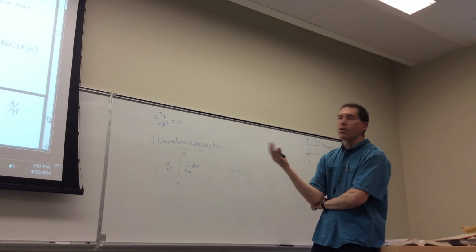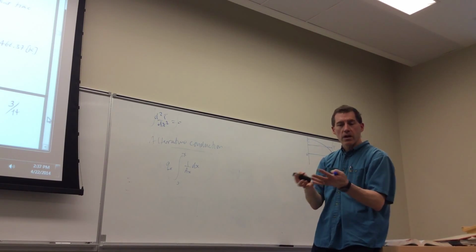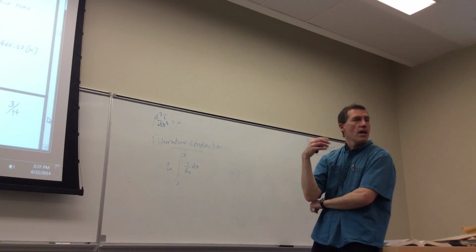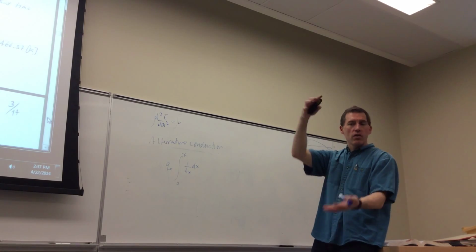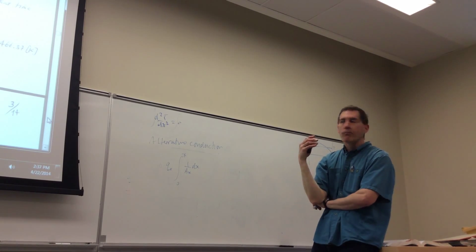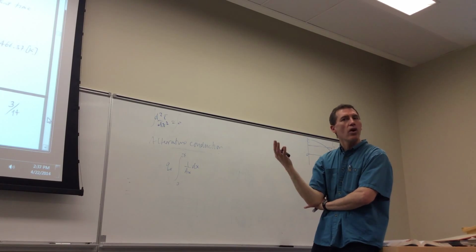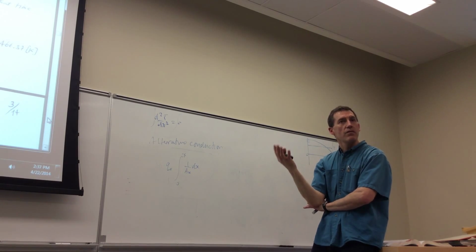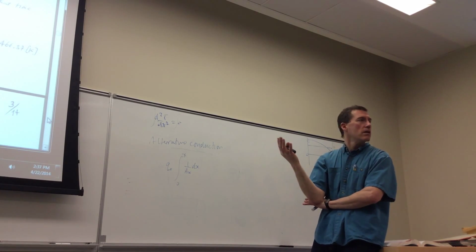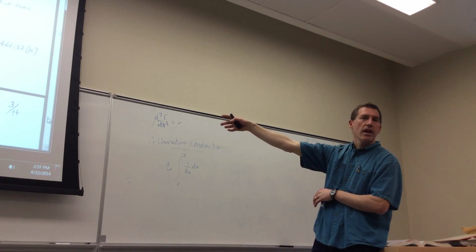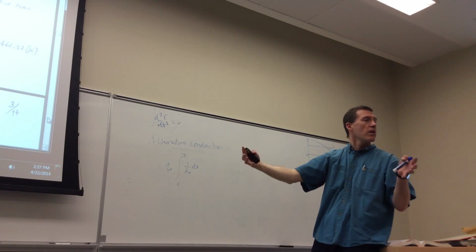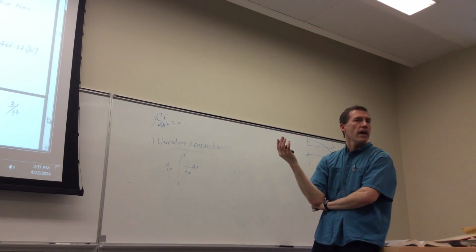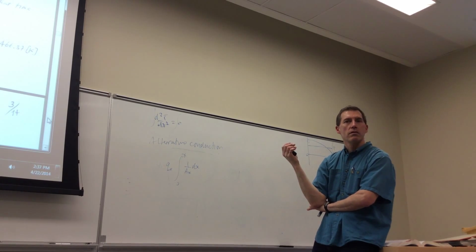So just be prepared. The only hard part about the heat exchanger problem is figuring out what geometry or what condition you have, what equation to use for epsilon or NTU, and whether you're calculating all or part of the overall U. Make sure when you do the overall U calculation, or the UA, to get the NTU, you use the total heat transfer surface area of the heat exchanger, the whole area. In that example with the annulus, it was easy, it's just the one length, but if you have more than one tube, you have to account for the surface area of all the tubes. Some people forget that when they do tube banks, for example.